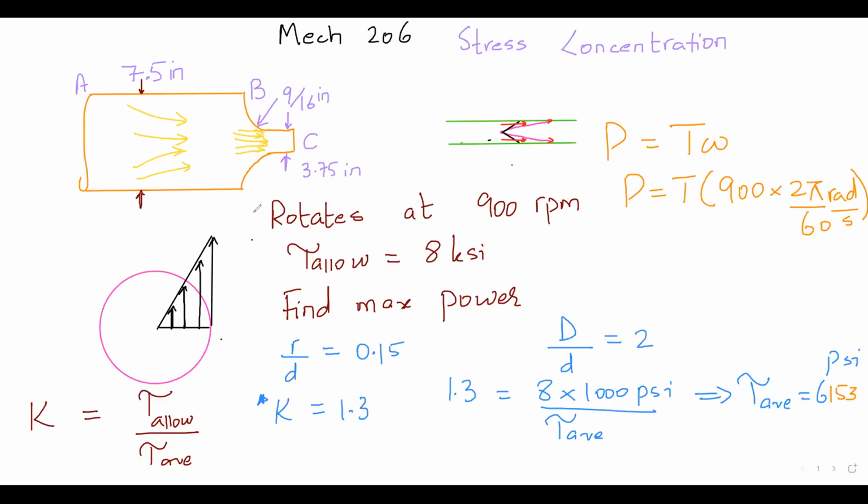Again, I have a circular shaft. I understand the confusion because when we talk about average shear stress, you are like, that's average. Why not maximum? You are talking about the maximum actually, because if you use this formula, you have equal to T R over IP, right? So what is this C value? This C value is the radius, the maximum distance from the center. So technically this average shear stress is giving you the value for the maximum average shear stress, that is this black line. My contention is that there is actually, because of stress concentration, a line that is this big and you are underestimating. So anyways,